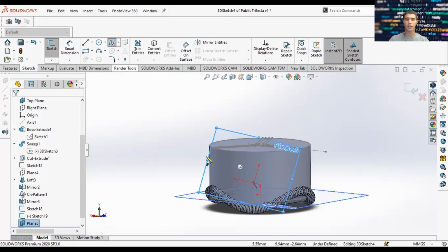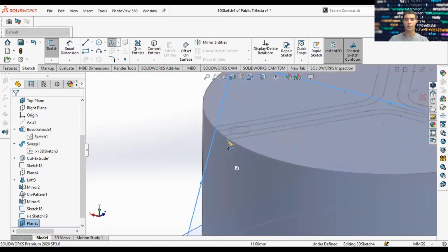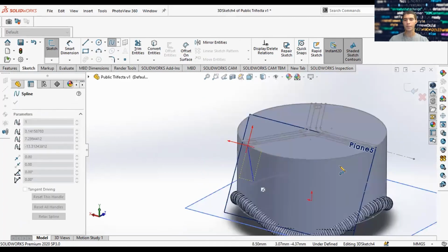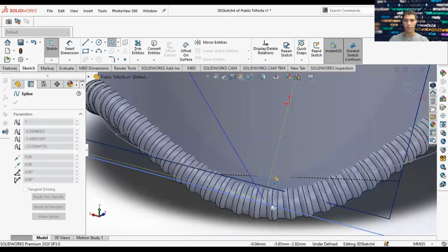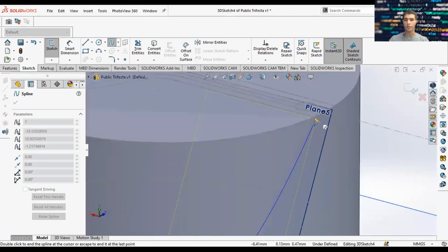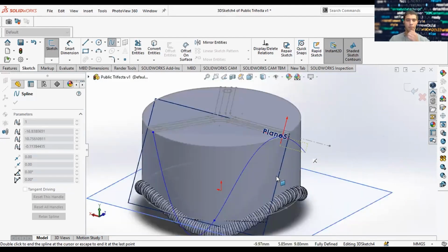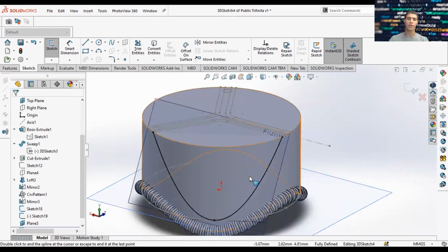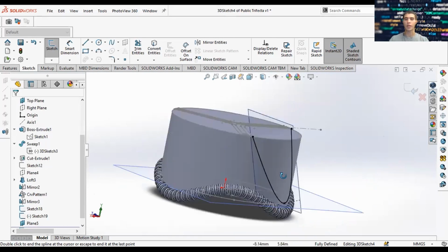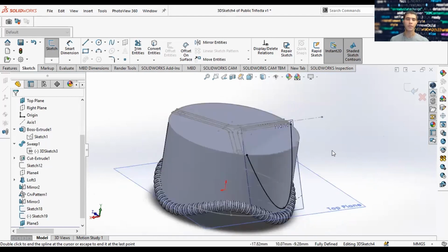And we're going to select the spline between this point, the point we selected down here, and this point. And once you're satisfied, you click escape. And you'll notice, instead of an arc, it does a spline. Particularly, splines are powerful because they're not defined by a certain geometry.